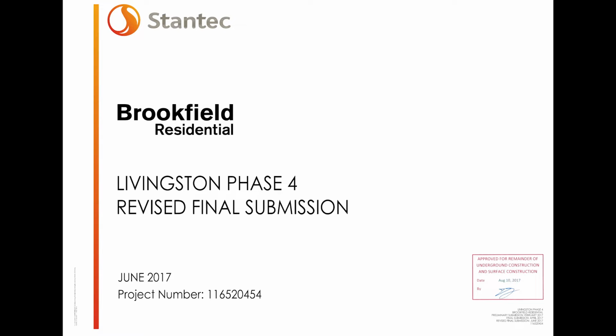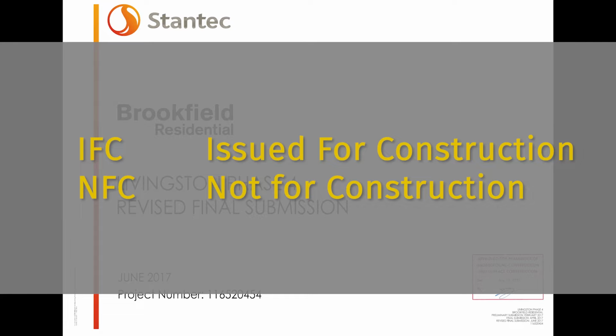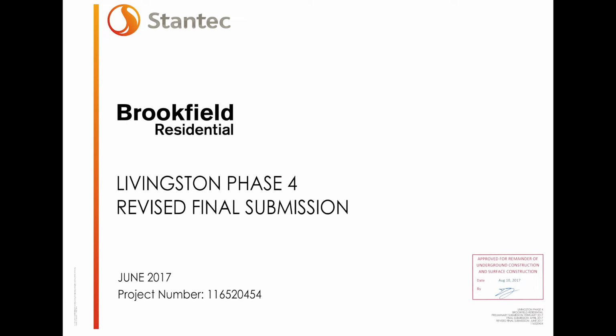Check with your supervisor or coordinator to ensure you are using the most recent revision. The IFC, or Issued for Construction label, states that the plans have been approved for construction to begin. Before the approval is given, plans are labeled as NFC, or not for construction. NFC plans are for reference only and cannot be used during construction. This set is revised for final submission, which would mean we should not be using them for construction. But there is a signed stamp in the bottom corner stating they are approved for underground and surface construction.